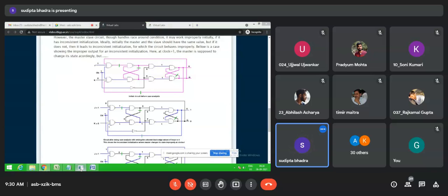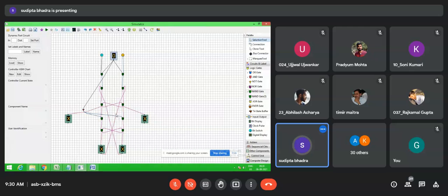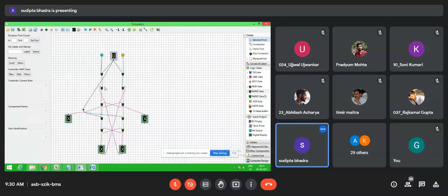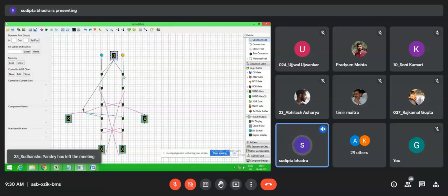So this particular circuit is a master slave JK flip-flop circuit, and you have to use it, because otherwise there will be a race around problem. Still the race around problem will be there, but you will follow this master slave design, not the normal JK. Now if I change it, let me change the circuit with 3 input NAND gate, so it will be clear to you.